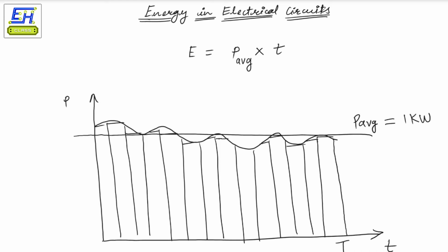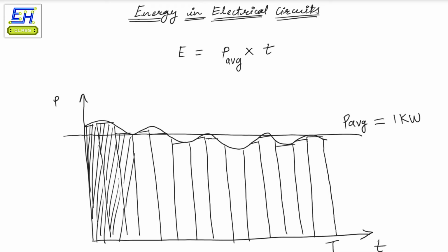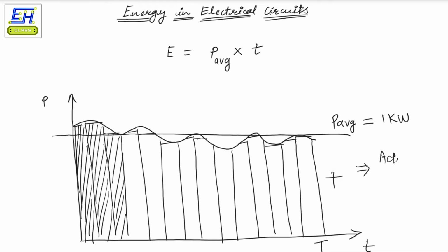And so most electrical measurement meters actually divide this 1 hour into really small segments. It is better if this measurement window is as small as possible so that it is more accurate, and then you record the energy chunks consumed over a period of 1 hour, and you just add all of them together to get the actual energy consumed.